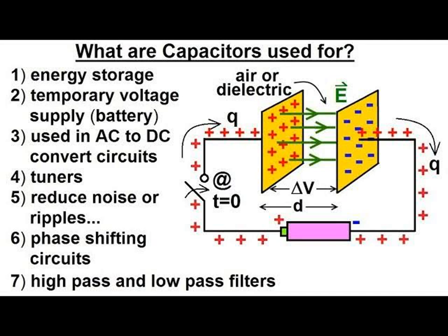As for the variable capacitor, they are adjustable. They have variable capacitance, which means you can adjust them to the size of the capacitance you want to use. It can come rated 100 microfarad. You can decide to use 50 by adjusting the plates. Now, what plates do you adjust? You adjust the set of semicircular plates that are separated by air or oil as dielectric. The semicircular plates are made of brass or aluminum.